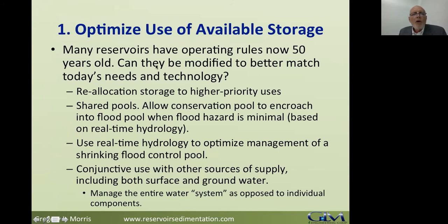So when we look at optimum use of available storage, you have to think that many reservoirs have operating rules that are now close to 50 years old. Can that operating rule be modified to better match today's needs and technology? You can reallocate the storage to higher priority uses. Shared pools: your conservation pool can encroach into a flood control pool when flood hazards are minimal. You do this based on real-time hydrology.